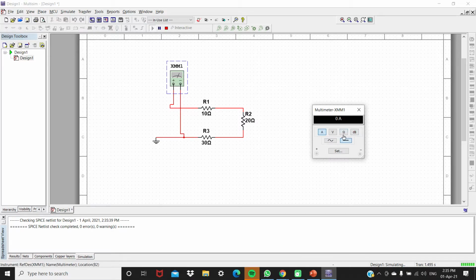Okay, go back and look at it. What's the ohm now? 60. You see, in real life, when you put the meter over there and you measure the ohms, it is not only measuring the resistance from the resistor, it is also measuring the resistance inside the voltage source. Now the voltage source becomes parallel with your resistors R1, R2, and RT. Now, this is the correct measurement. This is what the equivalent circuit should be.